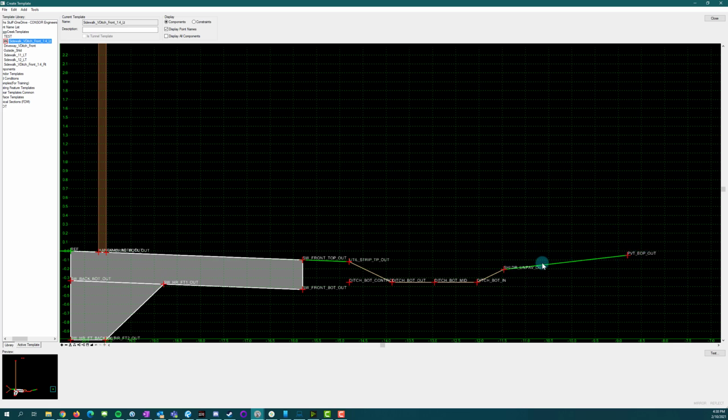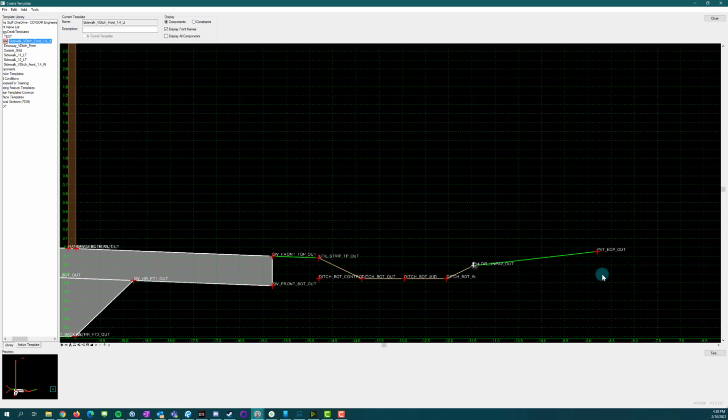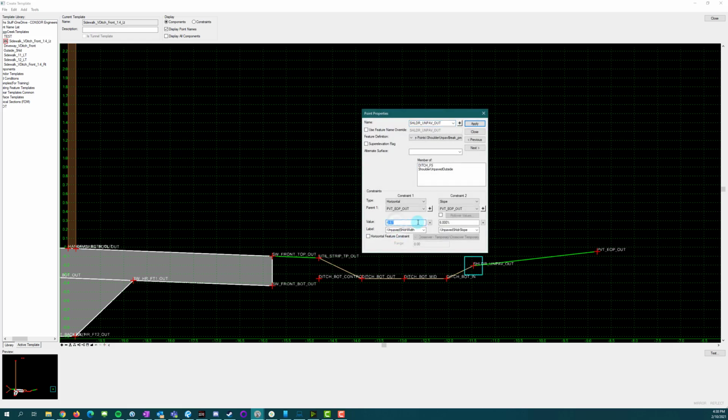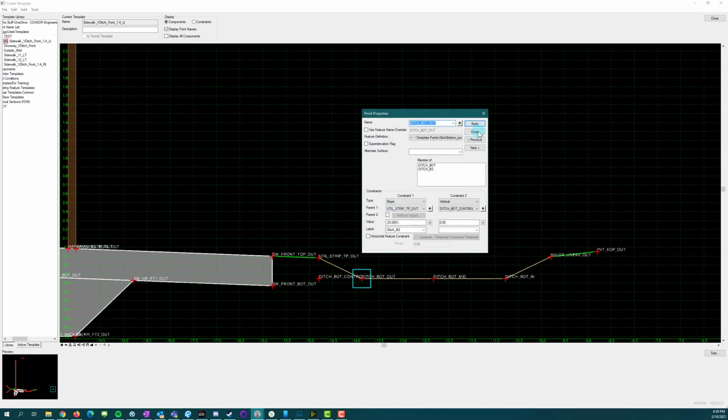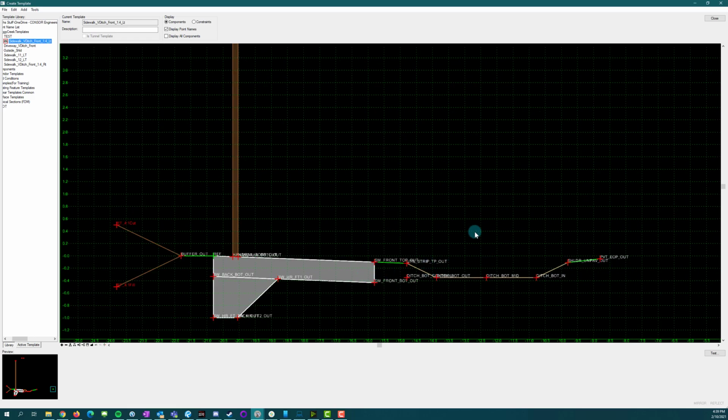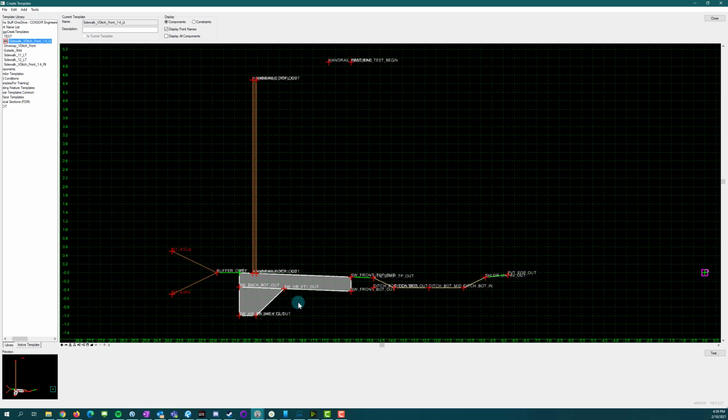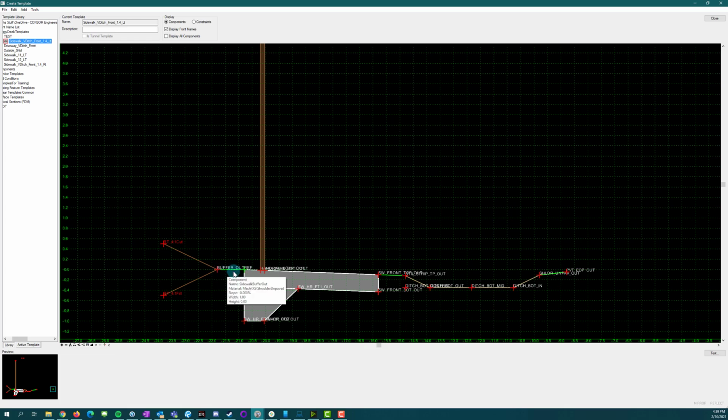So the project that I took this from basically wanted us to put a shoulder on this road a little bit before we went into the ditch. So it could be that this shoulder is just a little bit too big here. Maybe we have to reduce that to 1 or 0 for this to be able to work, so that we get that up a little higher. We could play with this slope a little bit, but I'm hesitant to make it any steeper than 25% because we're most likely still in this clear zone. I've been told that this roadway is 30 miles an hour, which has a 12-foot clear zone, I believe. So that makes me not want to go too much steeper than that. But since we brought this in 1, we could maybe even bring this into 0 if we had to, since we have a pretty smooth slope back here.